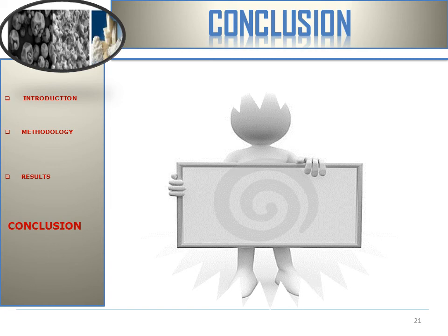The application of a PCM layer can minimize the temperature and relative humidity of the inner wall surface and the fluctuation of convective heat flow. It is concluded that the efficiency of the PCM can be improved if the building can be properly ventilated. So for that, in the next article we will deal with the integration of solar ventilation to improve thermal comfort and energy performance to achieve a positive building.